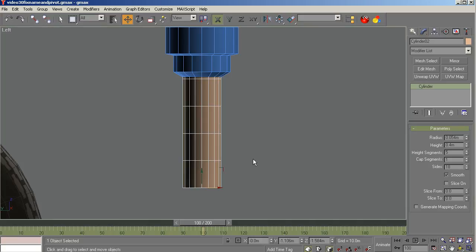These polys, these sides are a little heavy for this gear. You can easily get away with like 10 or 12, and it will look smooth as silk in the sim. So this is poly heavy, so 18 sides is just really more than enough, unless you've got it visually in your virtual cockpit. I would not go this high. If you're in FSX, that's fine. If you want to go that high and you're not concerned about your vertex count on your mapping sheets. So that's centered, as you can see by the line.